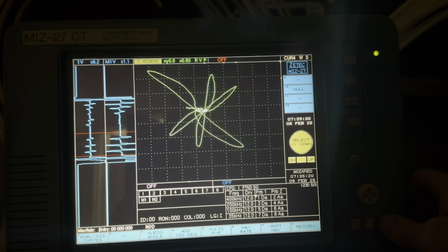For the 20%er, there's actually 4 flat bottom holes 90 degrees apart around the tube at the same axial location in the tube. And the reason they put 4 is because they're so shallow. To give the signal amplitude that we need to perform a proper calibration, they need to make 4 of them. Now, since they happen at the same axial location within the tube, and a bobbin probe averages the entire circumference of the tube and gives you 1 signal output, you get 1 signal even though there's 4 flaws there. If you wanted to see in your eddy current data that there was 4, you'd either have to use a rotating probe or an array probe because they have 360 degree resolving capability around the tube circumference.